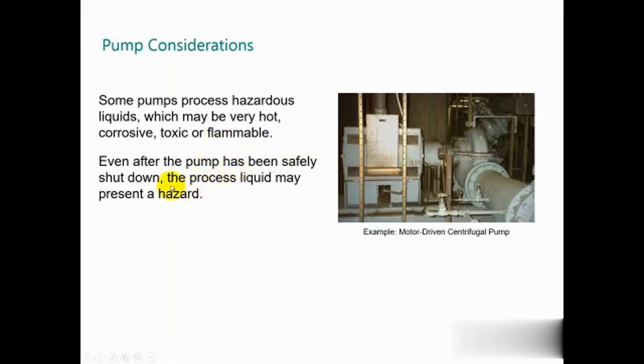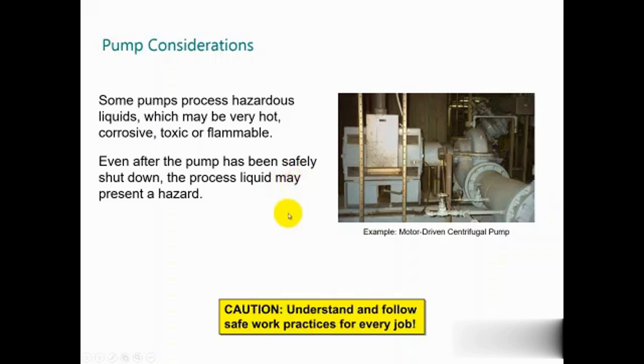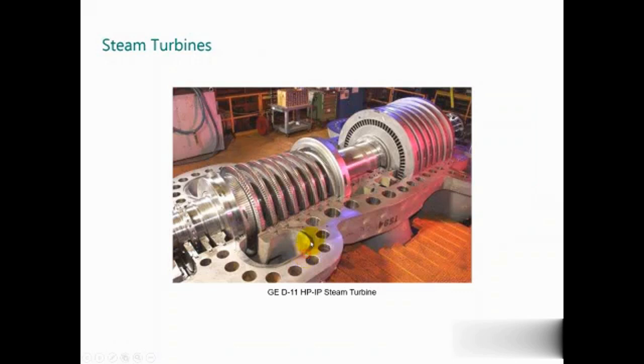People working close to the pump need to take extra care and ensure that all the lines are locked with the valves or any device for lock out to avoid any accident. Remember, understand and follow safe work practice for every job.